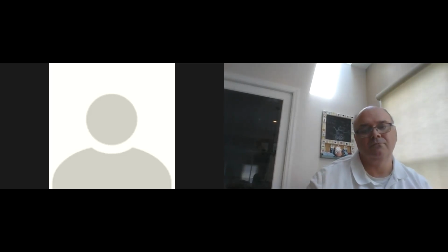Now, if you want to make standard messages, they have a standard IMU message or standard IMU raw message. So if you want, you can, and it's not hard to do that. You just have to import the proper message type at the top, and then down below create one of these messages, stuff the values in, and publish that.